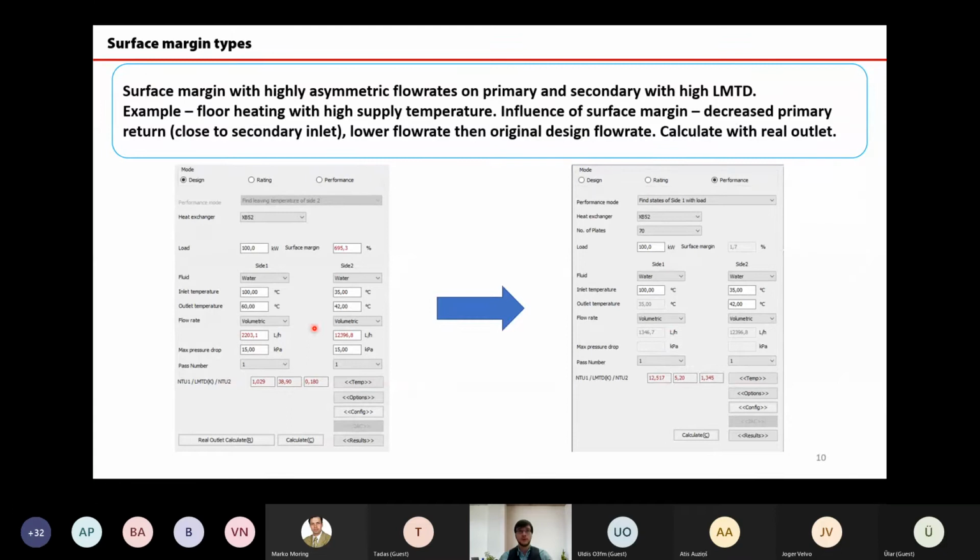And you see the impact here, it's already 2 times different flow. If somehow I also rounded up the valve which I selected, then I clearly have an overdimensioned valve, which might actually lead to big control issues in the system. So here, this is one type, quite often met, and it also creates a lot of confusion because it usually gives 100.